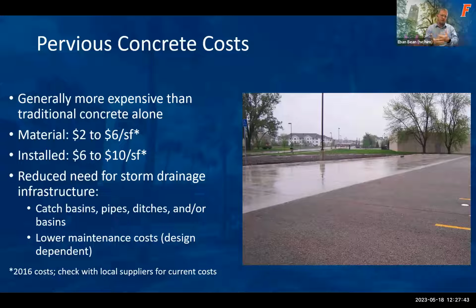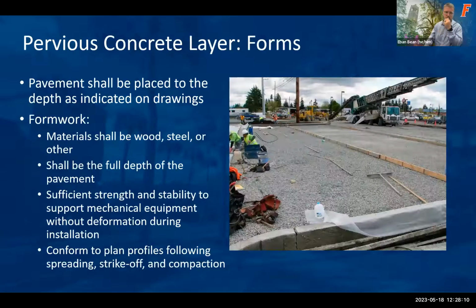But it's important with all these types of permeable pavements to understand and account for the offset of other storm drainage infrastructure, whether it's stormwater pipes, inlets, land area for stormwater basins, ditches, other things, and your maintenance costs can be reduced as well if you're making sure that you're not having sediment loadings that are contributing to the area or having too high of an impervious to pervious ratio.